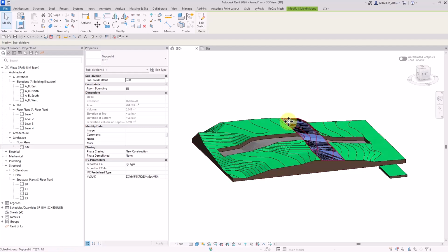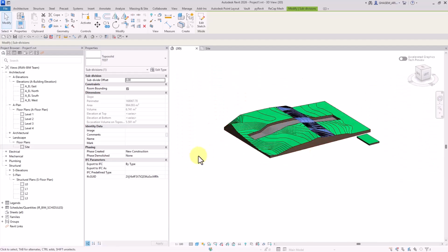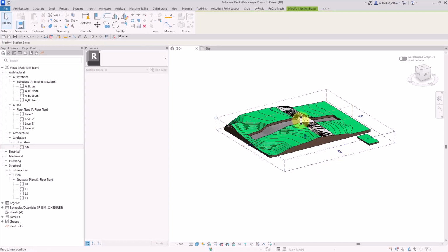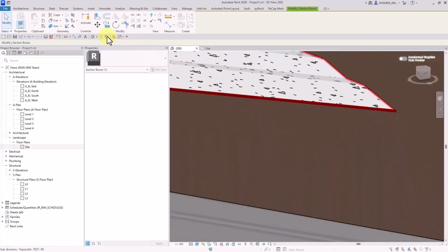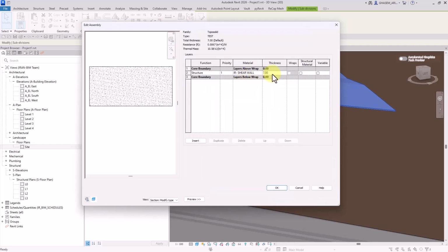Otherwise, we might face some errors and the element might be removed, and the software does this because it wants to prevent these errors and problems. And by the way, this value usually is 8 millimeters. Yeah, basically such a value would automatically be specified so that the element would be preserved. Alright, I'm going to go back here and set the thickness on 5 this time.